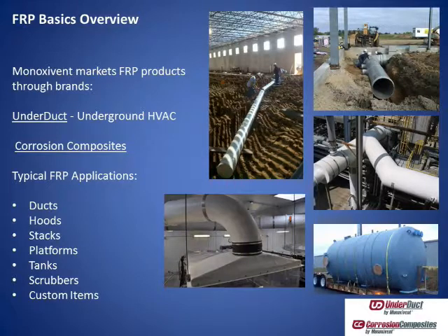And stacks have a unique problem. It's not just a duct standing on end. If you can imagine a large stack exposed to wind and seismic and extending up in the air without any guys or any supports, and now you put the wind load against it, not only do you have to use filament winding for the stack structure, you have to put in glass in the vertical direction to help fight that whip motion or the pressure that you get from the wind load.